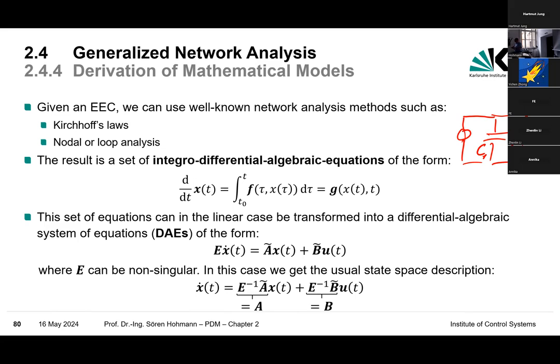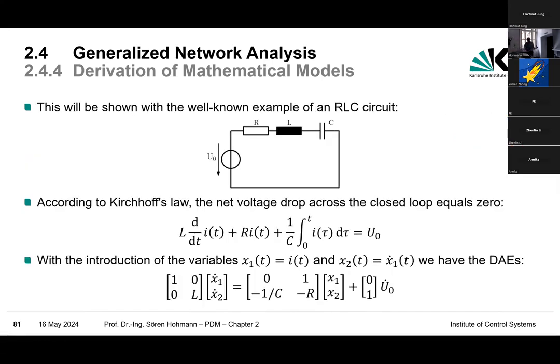And here's the problem. If we talk about state space systems saying the states are completely defined by the storages, that's not true. Because you can have such a situation where two capacitors are connected in parallel. I do need just one state to describe the entire system. And therefore, just to make an example where this is not the case, where we have a very simple situation where everything is needed, here an oscillator circuit